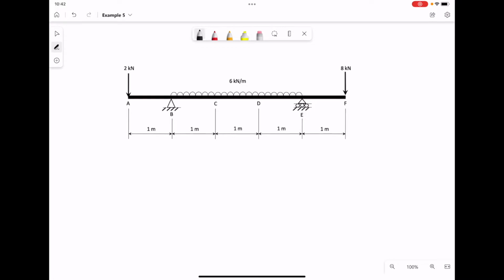We're going to start this problem by first of all drawing a free body diagram. In this, we're going to replace the supports with the associated forces, and if we have any weights or loads, we apply them with the correct force applied. In this case, we've got 2 point loads and 1 UDL. They are already in kilonewtons as a load, so we don't need to change them.